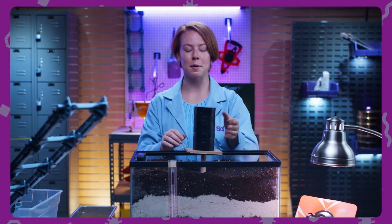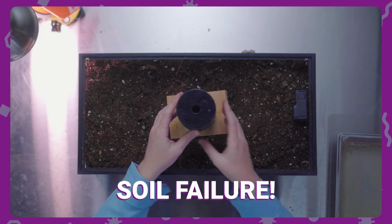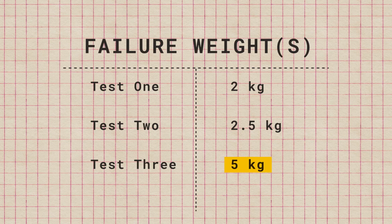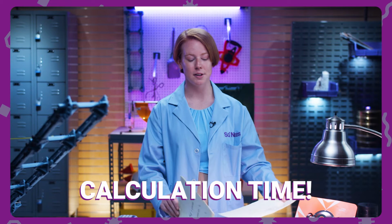And now at 5 kilograms, we can see that the foundation is wobbling a little bit, which is considered a failure. The point at which test 3 failed was at 5 kilograms. Now that we have our results, let's find the pressure experienced by the soil at the failure point for each test.